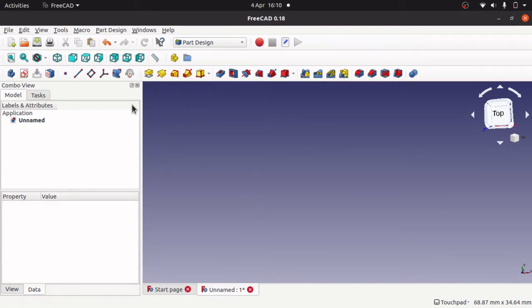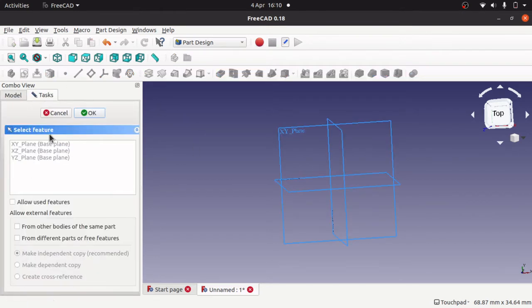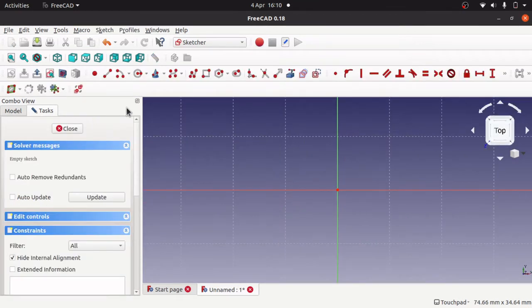And there's two methods with this one. The first method is a single sweep across on one tabletop. And the second method is to split the tabletop in two and use two sweeps and bring them together. So let's do the first one first. So create a body, create a sketch, and this is just for our tabletop.